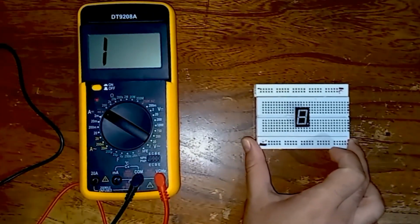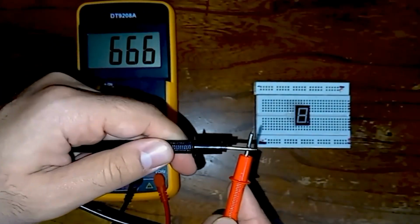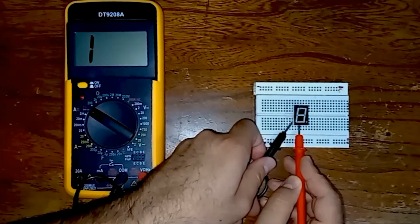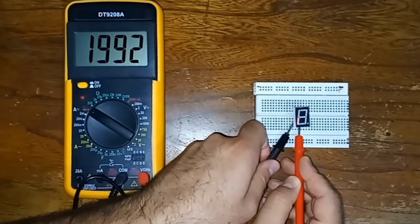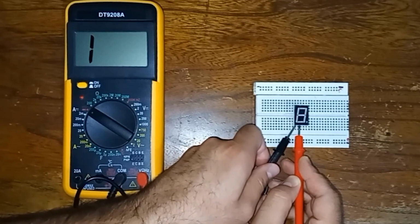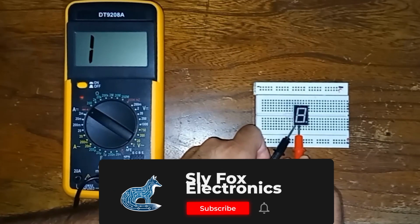Then prepare your 7 segment, and you can see that when these probes are connected together, they produce a sound. I want to say that they beep. And I connect the red probe to one of the common pins, and then connect the black probe to any pin. You would see that the LED of one segment is turned on. It doesn't matter which pin you connected.